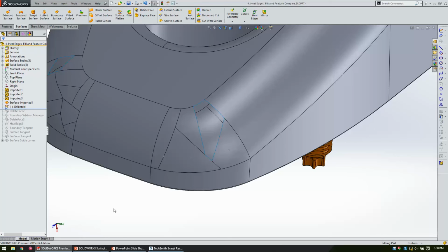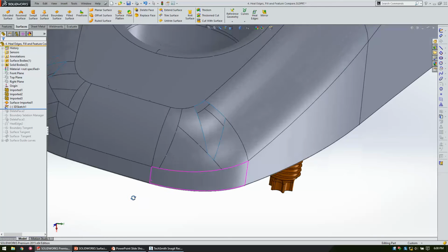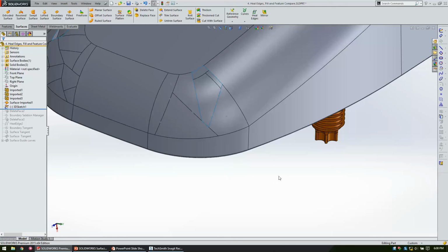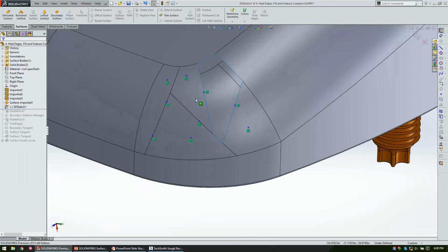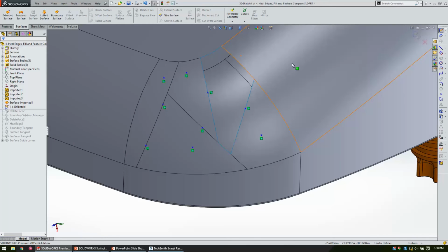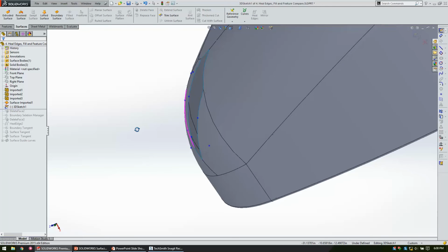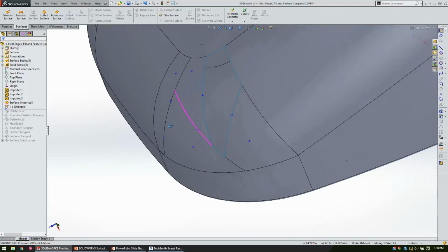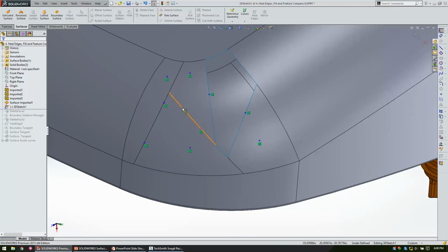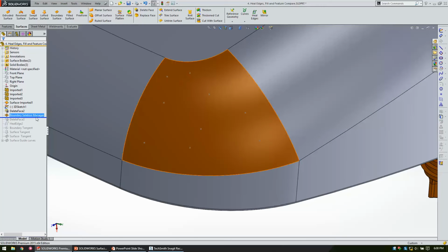So here's probably one of my most favorite tips and tricks that I hope everybody will walk out here remembering. You got to go 3D sketch points, put points in 3D space. So again, these are in 3D space, not on a plane, attached to the surface that you delete. And then you delete your surface. And then you would heal your edges in there somewhere.